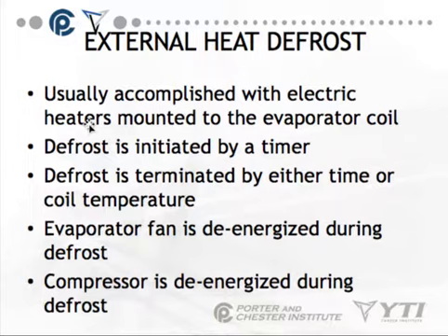The defrost is terminated, in other words, shut off and sent back to cooling, by either time or coil temperatures. The evaporator fan is de-energized during defrost, and the compressor is turned off during the defrost cycle if you're using electric defrost.